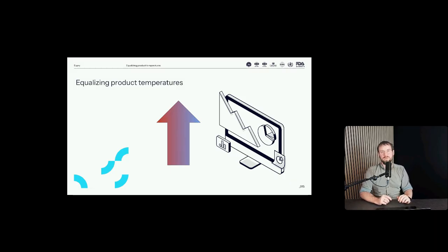For larger warehouses, it can be a more cumbersome process to fill up the space and then perform the mappings. There are a lot of different guidelines, especially in the ISPE guidelines for temperature controlled environments, about filling up parts of your warehouse and testing on a certain filling capacity, let's say like 80% full, and seeing whether that is still within the acceptance levels.